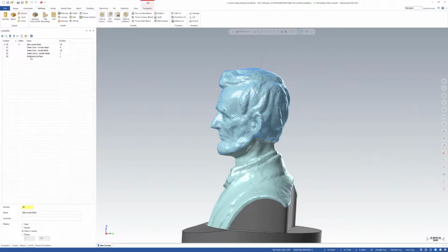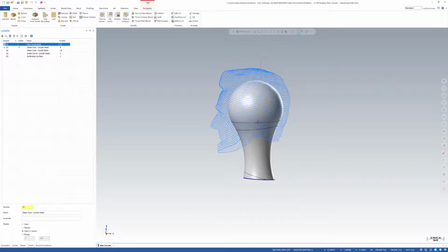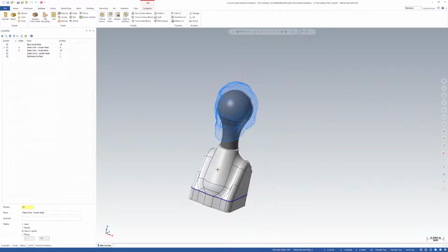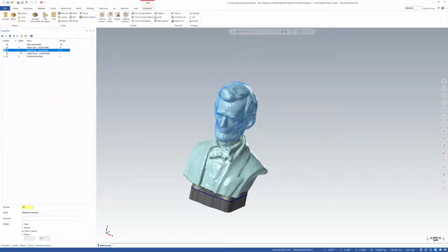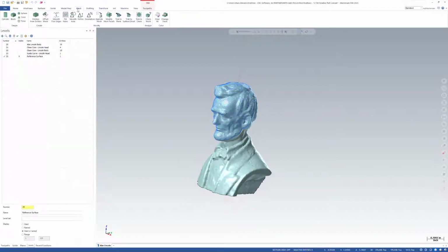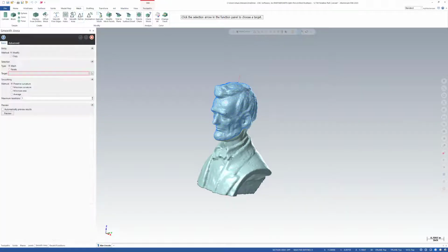So in the past, the way we would handle that is we would create these clean core surfaces. And this is a very manual process that becomes a bit difficult to create these curves or these bodies. I can assure you this took a long time to model all that. Whereas instead, what I can do is using a copy of the actual drive surface and our mesh tools, I can say, well, let's smooth this mesh. So let's grab this whole mesh here. And we're going to smooth out a lot of the detail. Let's say we minimize the area, 5 iterations. Let's see what we get.